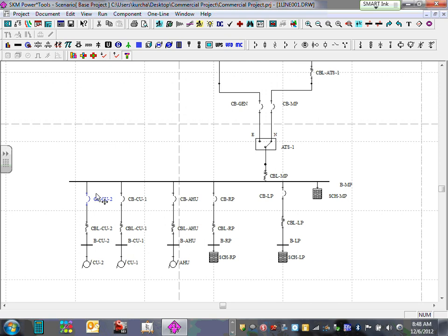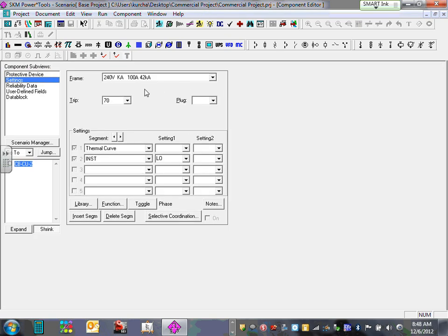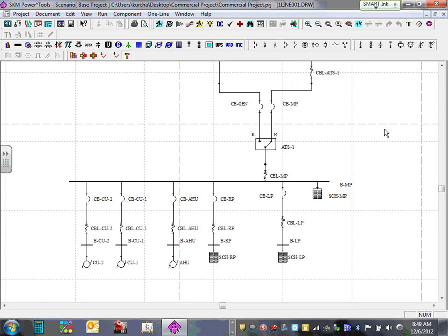Double click on it. The last one. I went to settings and I picked the 70. Yep. Now, like my friend Jeffy said, can I, Chad, go back and find a different type of circuit breaker that can give me 60? Absolutely. Now remember, guys, when you submit this as an engineering firm or the electrical contractor, you're liable. So if you're comfortable with this 70, I can go override the code and make it 70, Jeff, because I'm the designer. I can prove that it's safe enough.